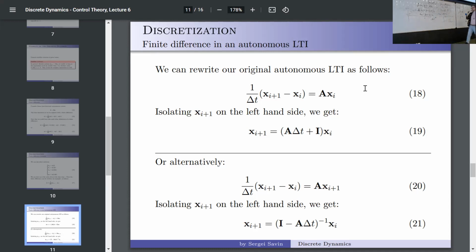Okay, so this is not a walk in the park. You need to consider the size of delta t in terms of numerical errors. It is absolutely a real problem, not something made up. Good for us, we find ways to deal with those things. It is not a completely horrible situation. But delta t, we don't usually get it like 1 over a million. Like 1 over 1,000 is more typical. Okay, good.